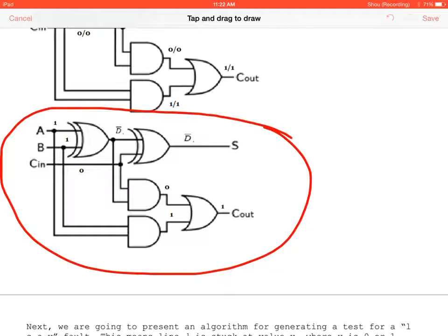It's going to propagate to the output, but only in certain circumstances because 0 is controlling this AND gate. The only time the error is going to propagate, if we look back to that truth table, is when carry in is 1, because it can propagate V bar to the output. So that's where these concepts of observability, controllability, and coverage come into play.